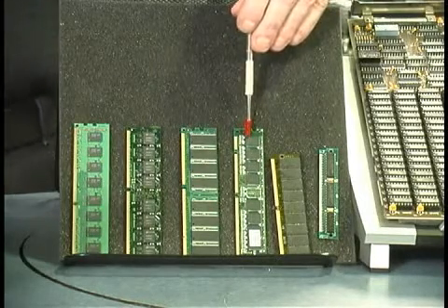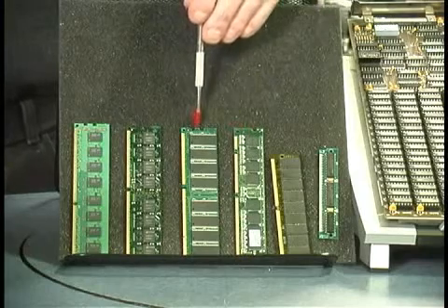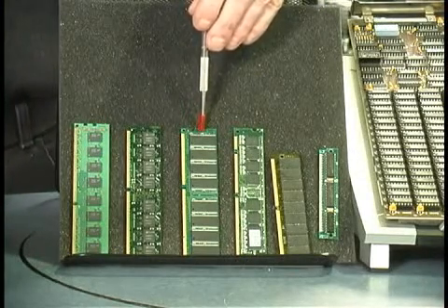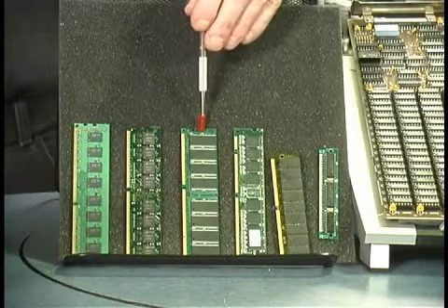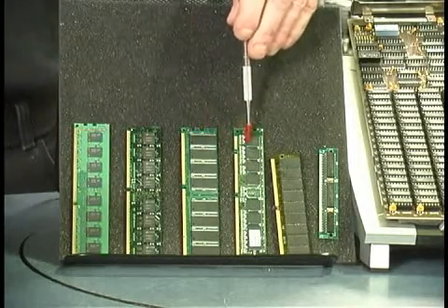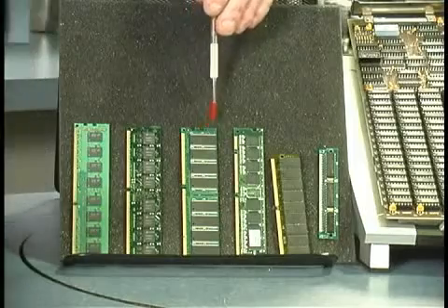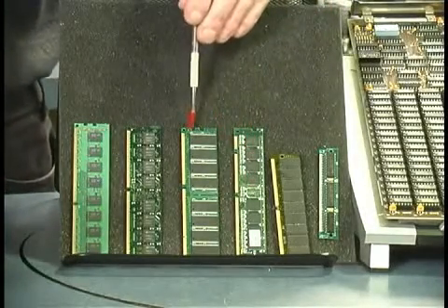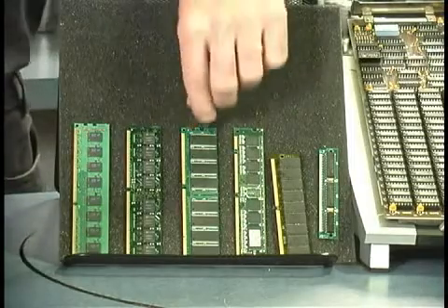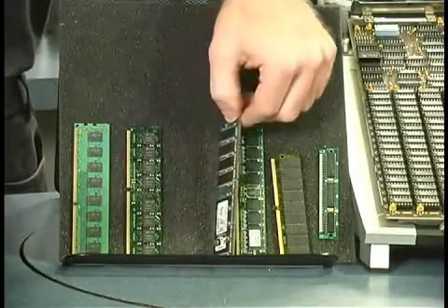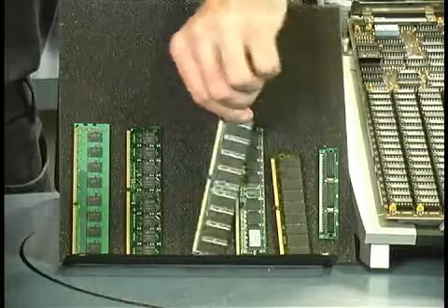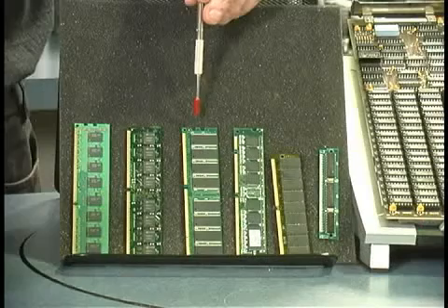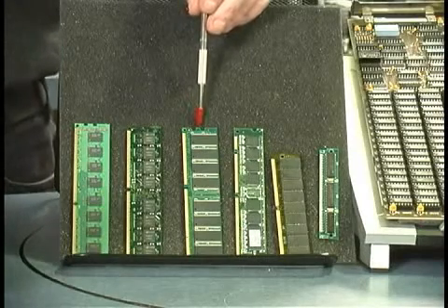Now, starting in 2002, that was replaced by something called DDR SDRAM. The DDR stands for double data rate, and just as the name suggests, it ran twice as fast as the single data rate. So these modules were different. They were not interchangeable, with a different set of contacts. And these were also DIMMs, being that the memory contacts were on both sides, and they were different. So now we had twice as many contacts without having to have the module be much longer. So this is the DDR DIMM.